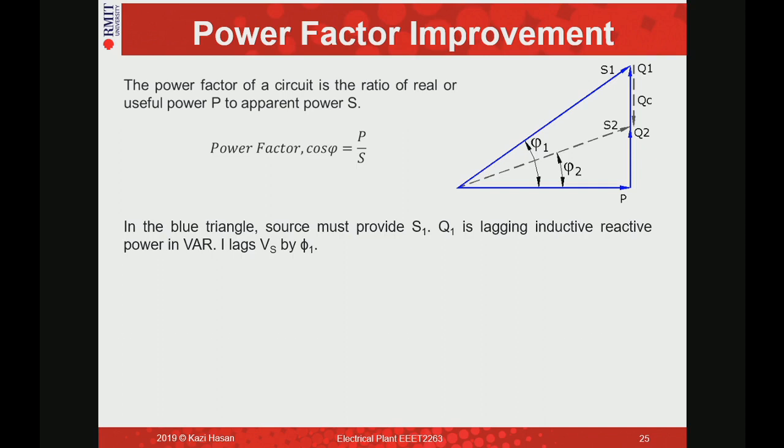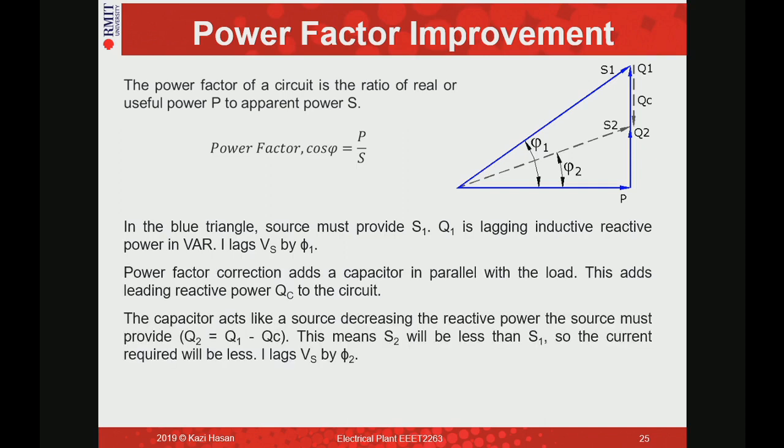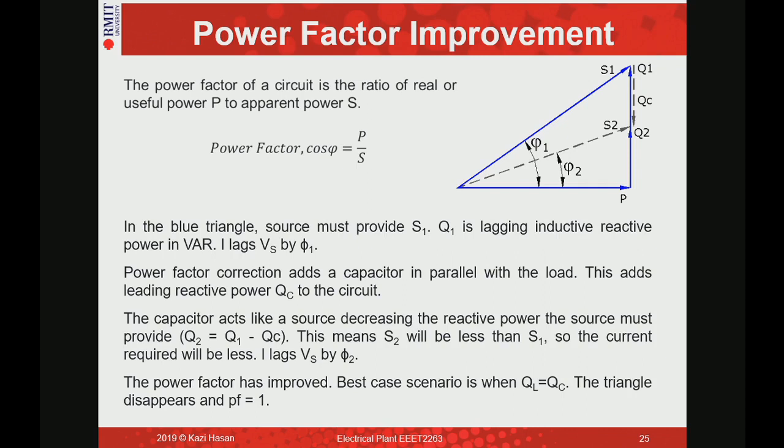So from this power triangle, just what we have said here, once we have a certain system and we need to do some power factor correction, then we determine how much power factor we need. For example, in a system you have 0.8 power factor. Now the utilities want you to have 0.9 power factor. So your power factor needs to change.